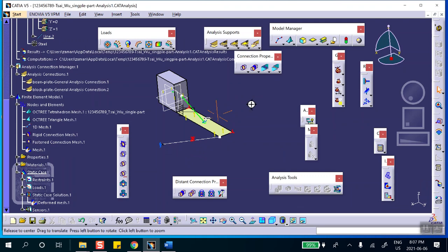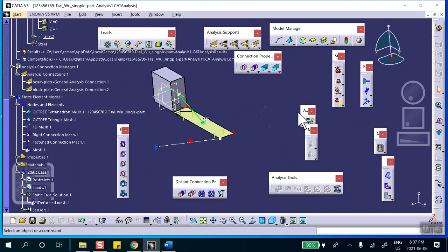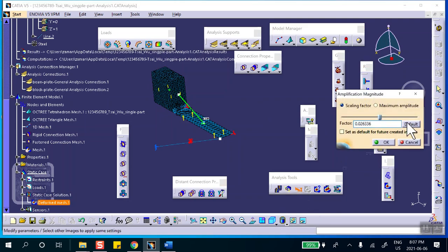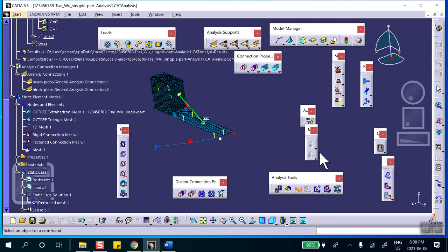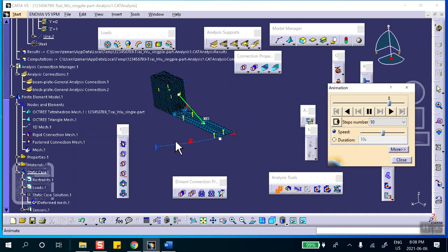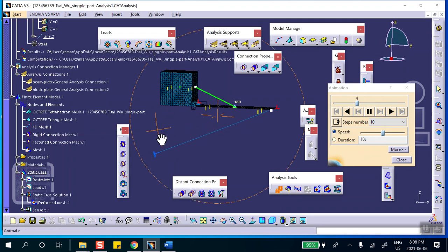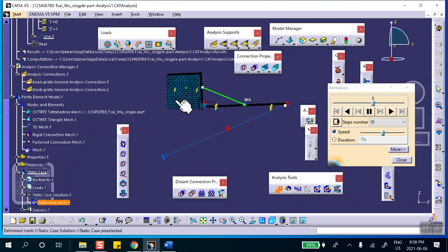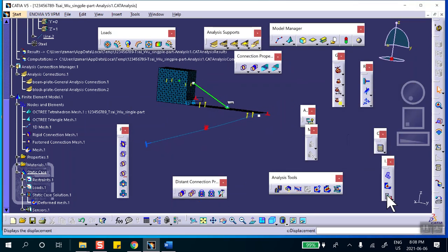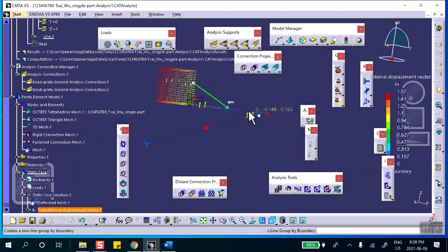It looks like it ran. There was no problem. Okay. So deflection. Change the scale. There we are. Isn't that the way it's supposed to do it? Sagging under its own weight. See that? Sagging under its own weight. Okay, good. Do you want to look at the magnitude of deflection? No problem. There's the size, 1.57 inches. That's probably a lot of deflection.